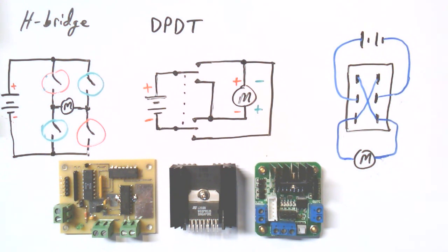One word of caution, and I'll remind you again if you do want to fool around with one a little bit: the fooling around would definitely mean really getting to understand it. As always, don't trial and error. They burn up quickly. This is the one we burned up a few because we didn't read the fine print on the 20 milliseconds between changing a bit value, and there was shoot-through that took out the chip. So, of course, don't just try stuff, just learn it, know what you're doing, and then implement it. That's how we need to fool with that. All right.